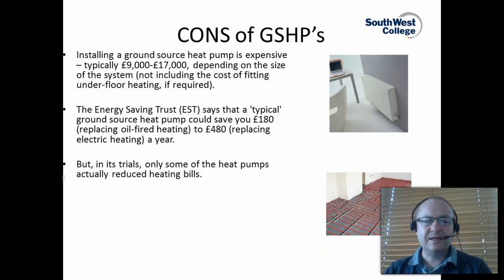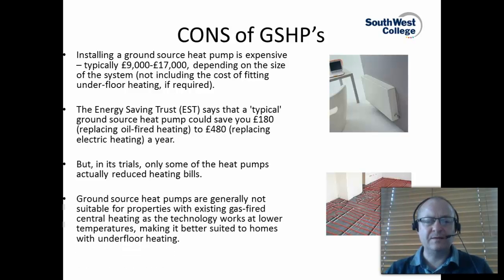But in the trials that the Energy Saving Trust run, only some of the heat pumps actually ended up in clients having reduced heating bills, and that was basically down to issues with the systems not being correctly sized. Ground source heat pumps are generally not suitable for properties that have existing gas-fired central heating, as the technology works at lower temperatures, making it better suited to homes with underfloor heating.